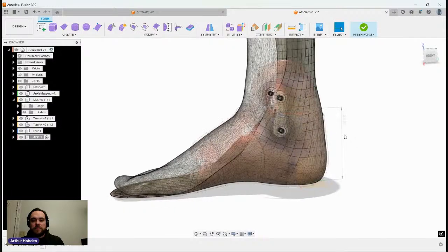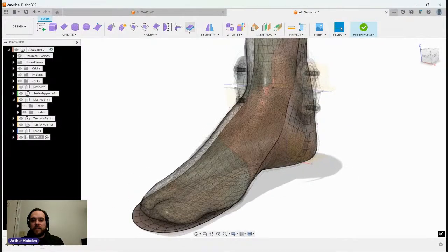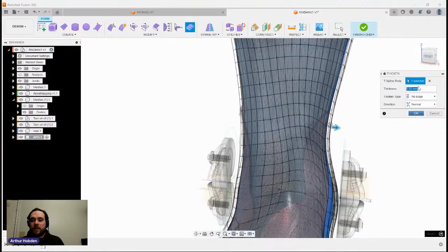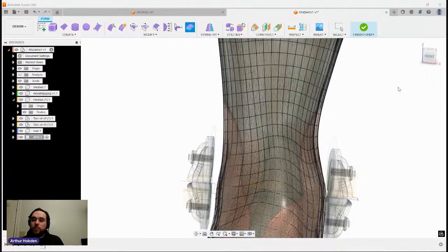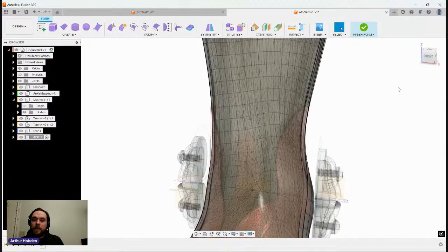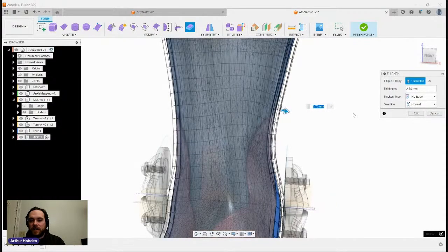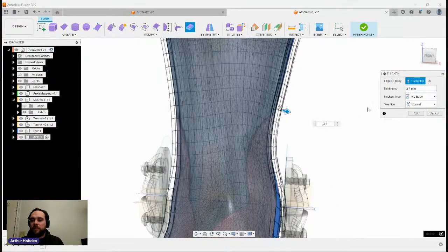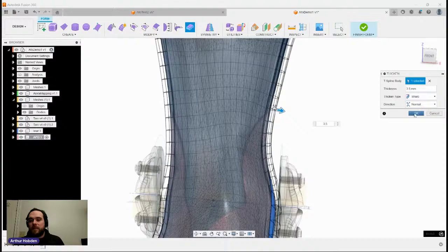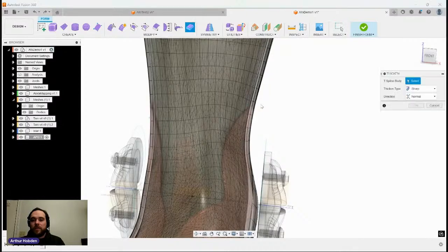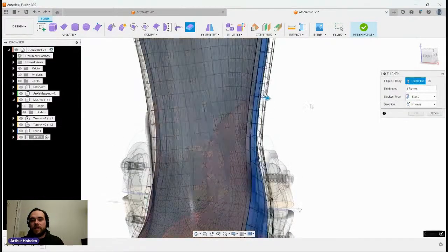So now we got to do something similar here. We got to thicken this, but this time we got to thicken it without connecting them. So we're going to create that clearance from the liner. So the liner was 2.5. We're going to create a surface at 2.7. Then we're going to repeat that thicken on that 2.7 to, let's say, 3.5 millimeters, or 4 millimeters. It's a good size for an AFO in terms of its thickness. Actually, I might just go 4 because 4 seems to be a bit stronger.